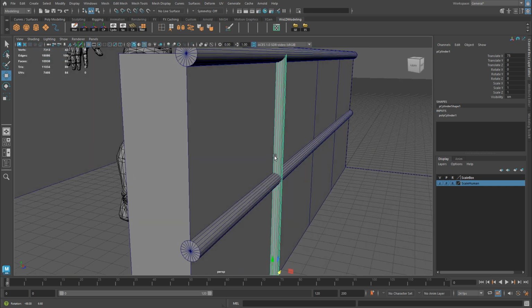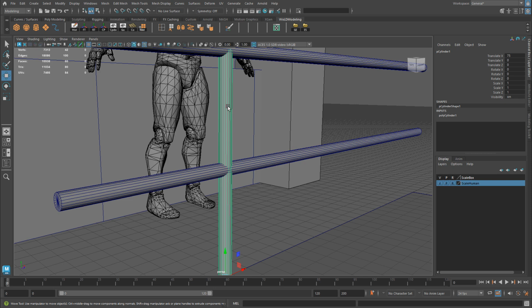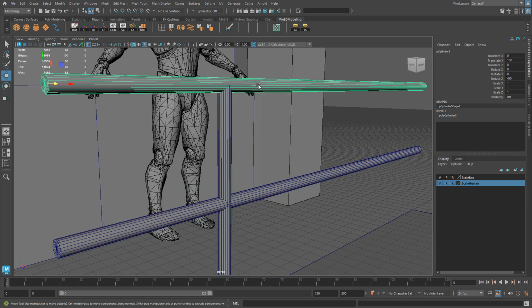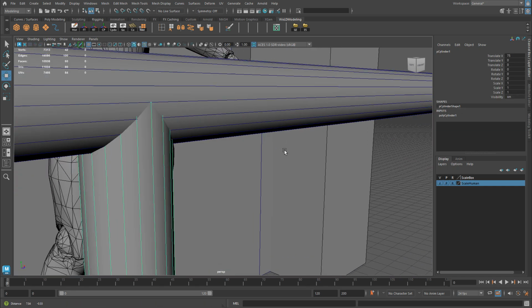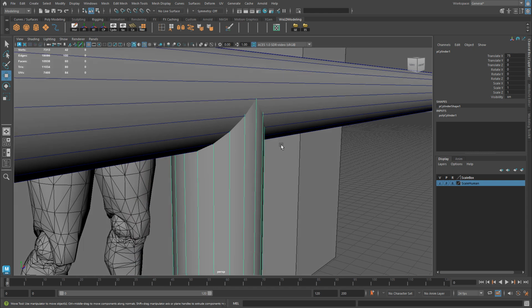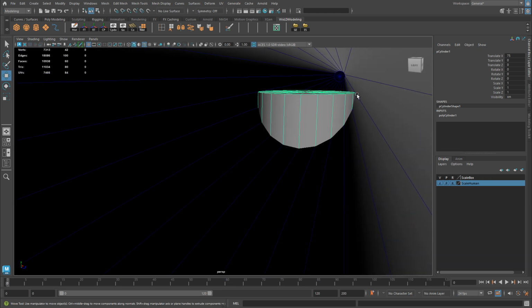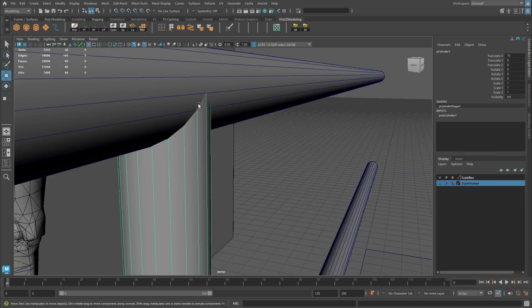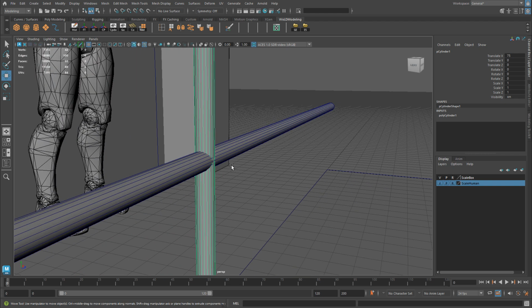Now, one thing to note, let me move this template temporarily out. The size of the cylinder right now is at 3 units, the radius, same as for the horizontal pieces. However, when you take a look at this, there might be slight overlap or Z flickering, Z axis fighting, due to the overlap and how this piece right here on the edges is overlapping with these faces right here. And you might get some problems right here for this railing piece.